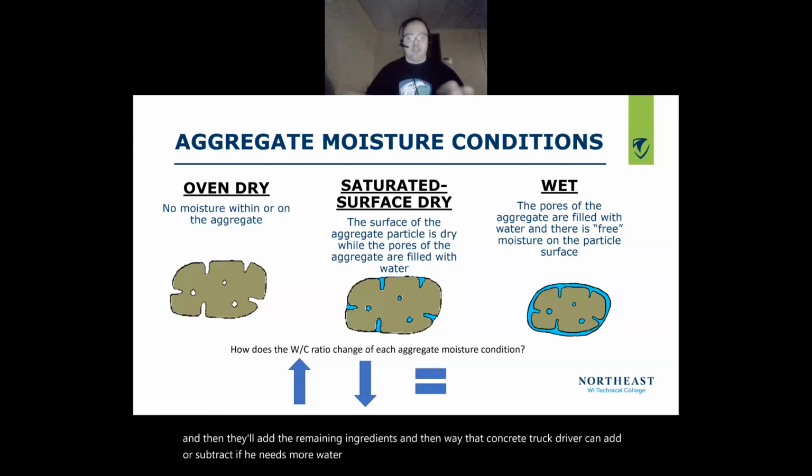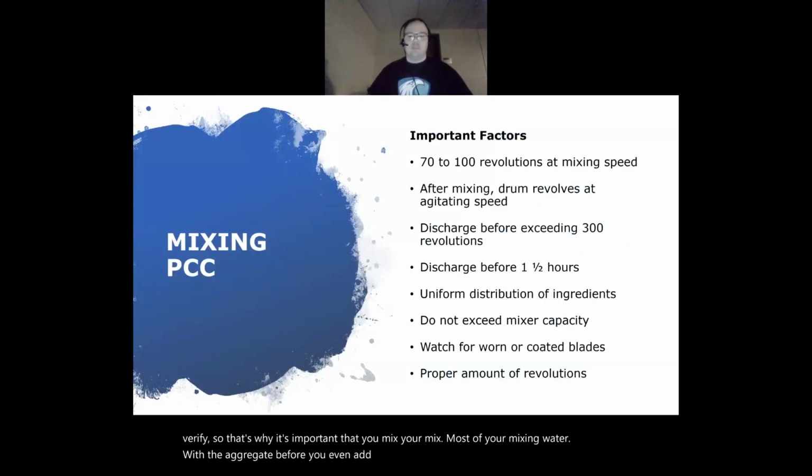So that's why it's important that you mix most of your mixing water with the aggregate before you even add the cement. Okay.